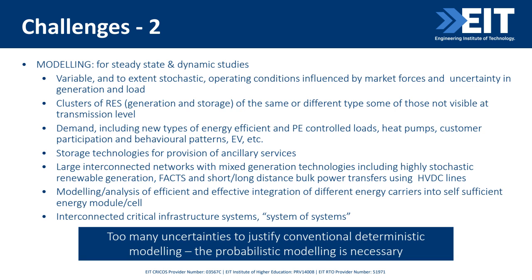Then you've got a problem with demand. How do I model the demand? Because I've got new types of energy efficient and power electronics control loads. I've got heat pumps. I've got customer participation and behavioral patterns. I've got EVs, as I told you. Storage technologies are also a very difficult thing to model because you've got all these ancillary services.